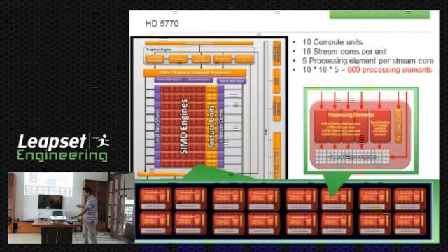In addition to that, it may contain some other support electronics. L2 cache is there inside the card, so that it can manipulate data very fast. Also, there's an outside memory controller, and this memory is placed outside the processor on the card. Right? It may contain 512 MB or 1 GB of memory. You easily load the data into the memory and run the kernel. Each and every kernel is run inside one of these processors. So you have 800 parallel processing units in the graphics card.